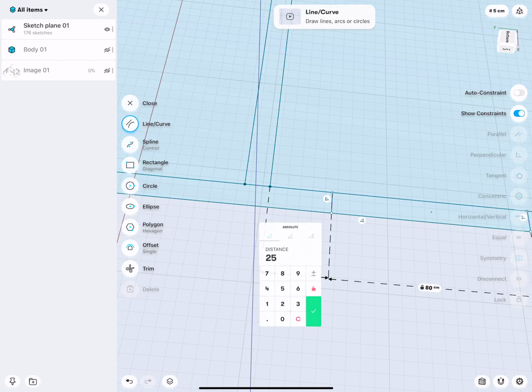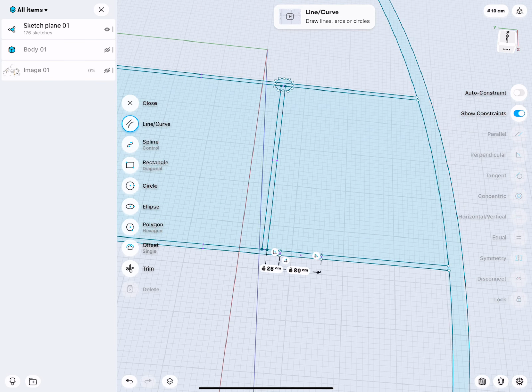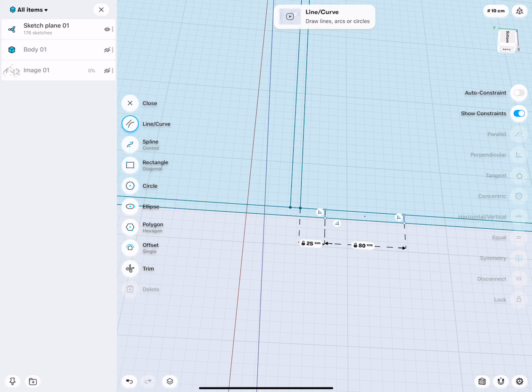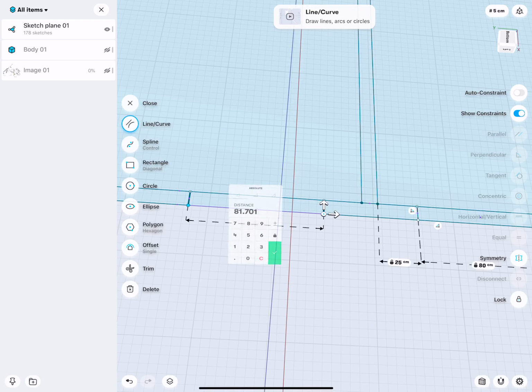The nice thing about these constraints is, as you can see, I can via dimensions move everything and not via a move command. I have to make this work really well, obviously, stabilize also my sketch, but this is not really much work. And then afterwards it is very, very easy parametrically to quickly adjust everything. So also here 80, this should be horizontal.